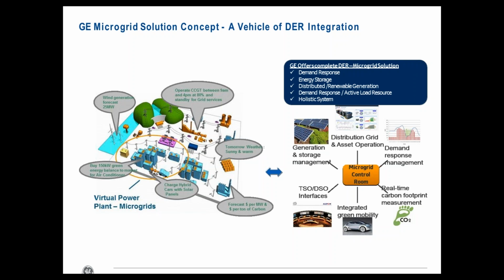And then, of course, GE is very much involved at all levels of the technologies required, from generation and batteries to microgrid control and distribution automation. The key message we would like to give here is don't be too purist about how you're looking at microgrids. Some people say it has to island and things like that. That's probably true, but look at the different functional building blocks within a distribution system as potential microgrids or nanogrids in the future, and how they interact on different layers.